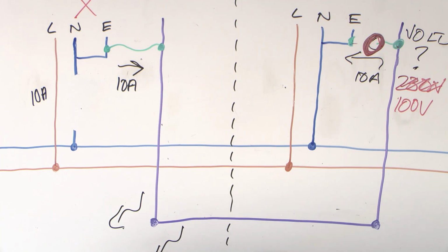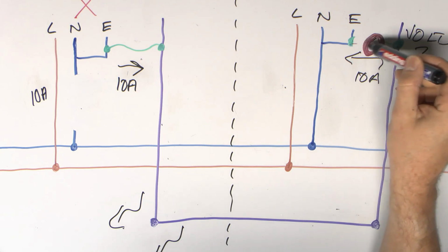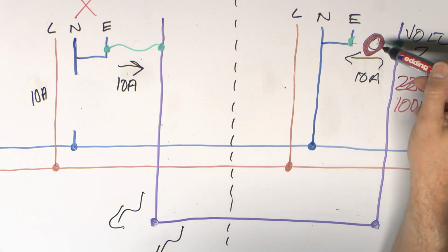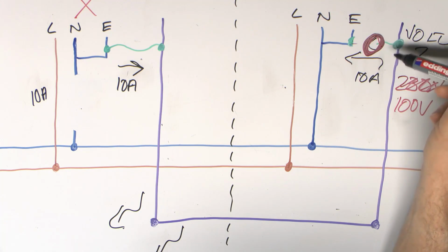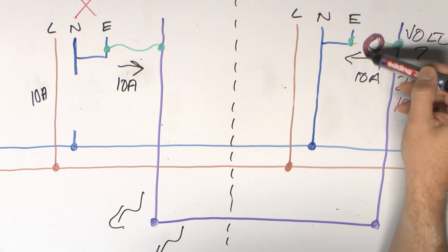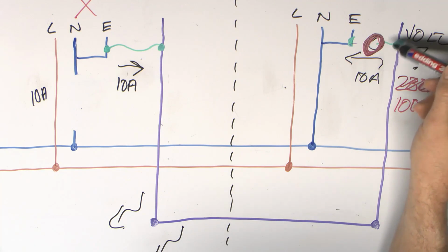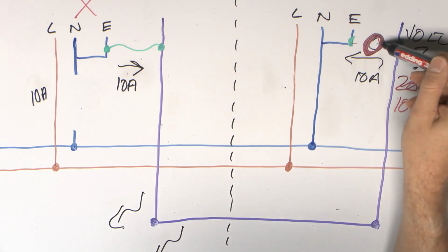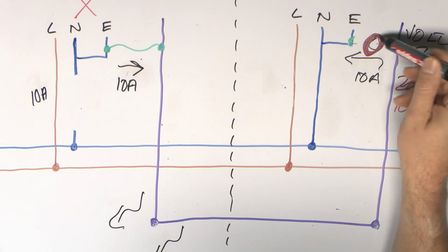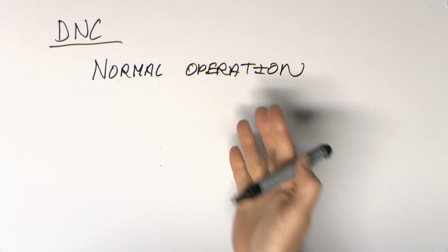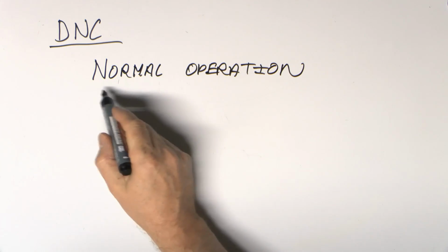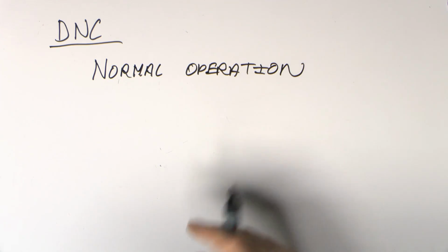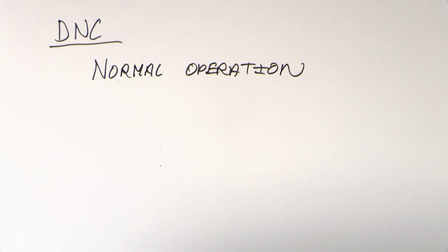same direction. So the main point here is if you've found current on a bonding conductor, when you disconnect it you may find that there's no voltage at the end of it, in which case it's normal operation, or if there is a voltage here, something is wrong somewhere else down the street or across the road or wherever else, and you can have a dangerous voltage at this point. So some current on the main bonding conductors could very well be normal operation, so it's pretty much inevitable because you've got parallel paths there for the return current from the installation.